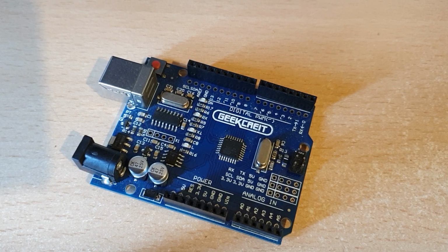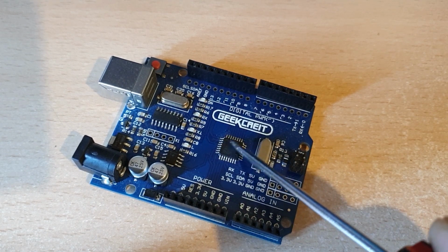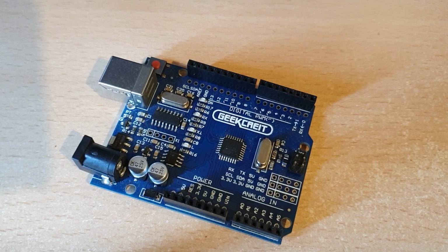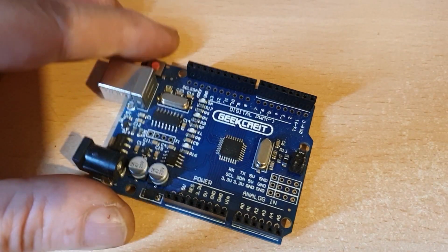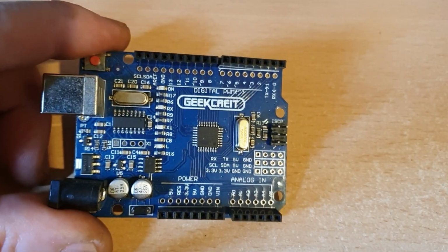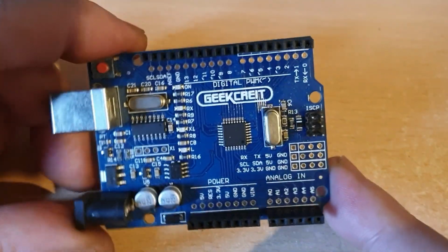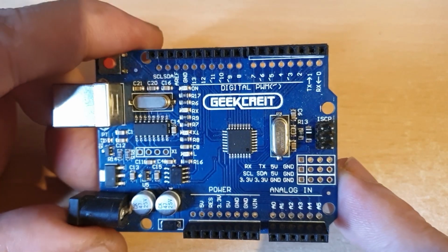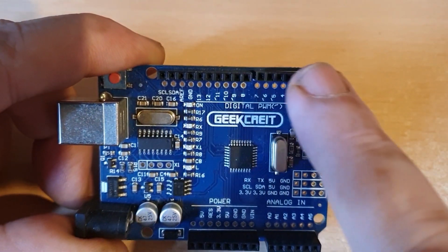In the middle of the board there is the microprocessor, which is a tiny computer that will use what it receives from the inputs to control what happens on the outputs, following the rules that you will set in your code. You could for instance have a temperature sensor connected to one of the inputs and write some code to switch on the heating if the temperature falls behind a set point, or turn on a fan if the temperature gets too high.